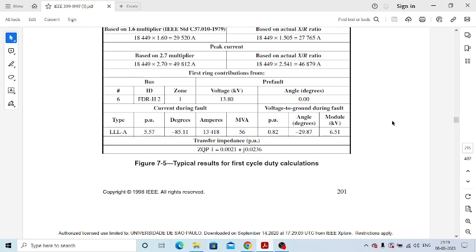The short circuit ratio at the locations where generators or equipment are going to connect is less than 3 in many locations in the Australian grid. These become important aspects from the power system operation perspective.